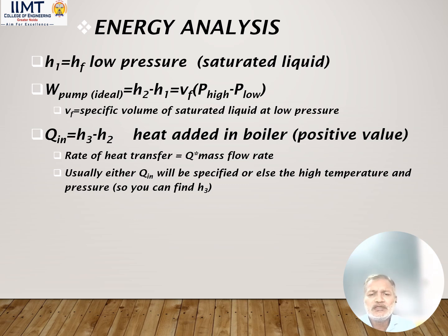You can purchase a steam table in SI units, and further, from the problems, suppose the problem is given that the steam is expanded from 10 bar, 300 degrees Celsius. So for this data, at 10 bar and 300 degrees Celsius, you will have enthalpy, entropy, every property tabulated in the table. So you can find values from the table and then calculate. For saturated liquid there is a table, with the first property HF. So you can find it from the saturated steam table.